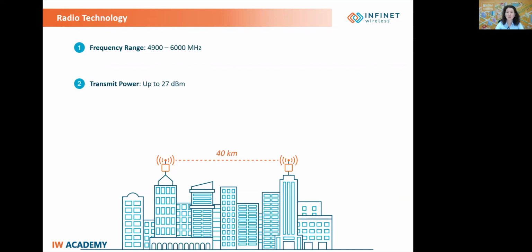We mention here as important as well that the maximum transmit power at the highest modulation is one of the key performance metrics, allowing Quanta 5 to achieve the highest performance over long distances and in noisy environments. The Quanta 5 transmit power at QAM 256 is up to 24 dBm, which is one of the best in the wireless marketplace today. Notable as well is the receiver sensitivity that goes down to minus 100 dBm, a very low level at which signals can be heard by the receiver.